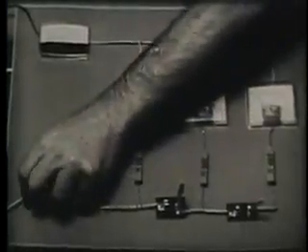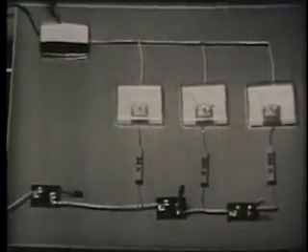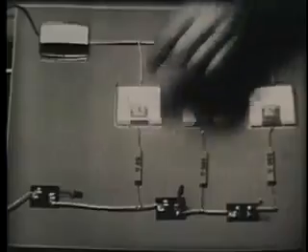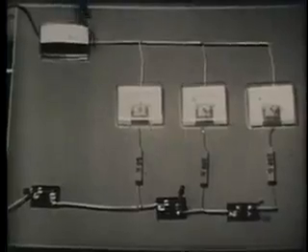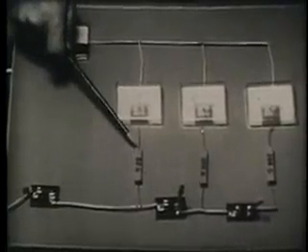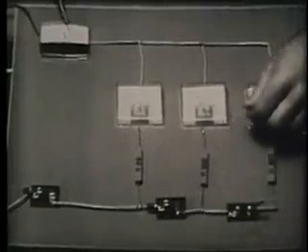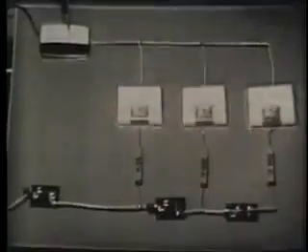For example, when we open all of these switches, there's no current flow because there's an infinite resistance between the terminals of the battery. When I close one switch, we have current. The added path then reduced resistance from infinity to a specific value. Adding another branch increases current, so total resistance had to decrease. Adding still another branch increases current, total resistance decreases.